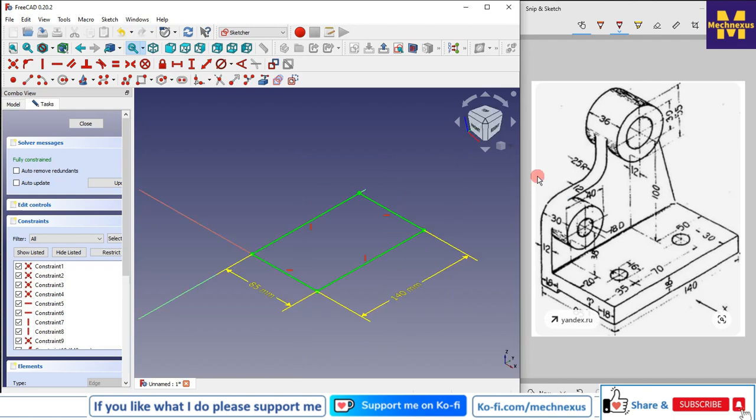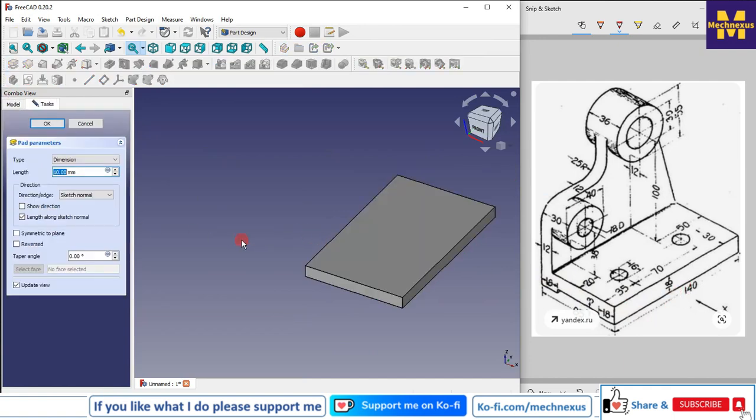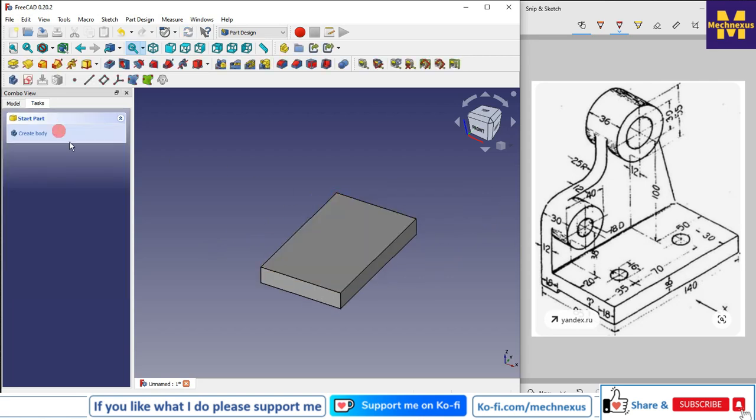Now I will come out of the sketch, and this pad is 18 mm thick, so I will select the pad tool and give the 18 mm, and I will close it. So this is our base profile, and now we will create this profile.